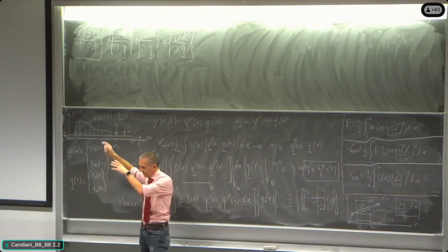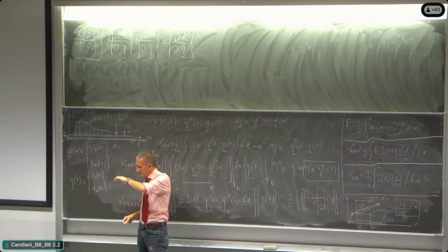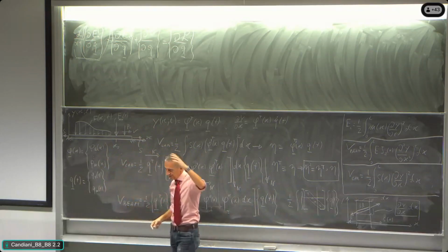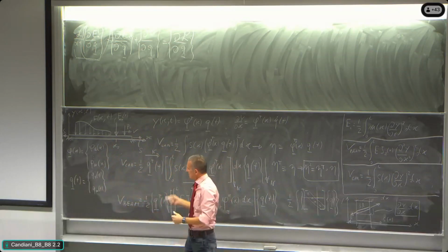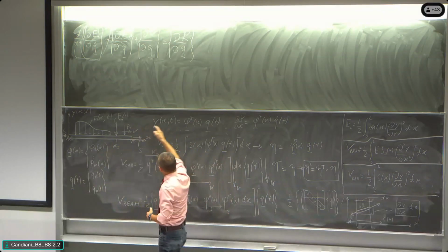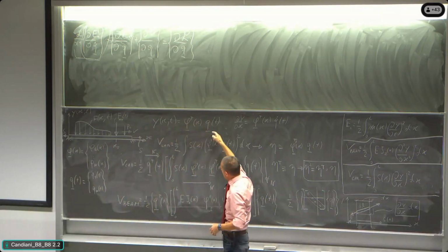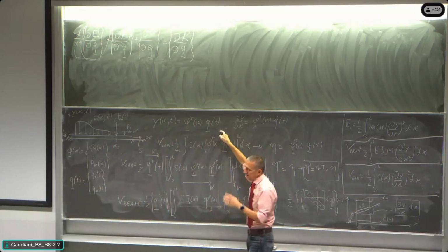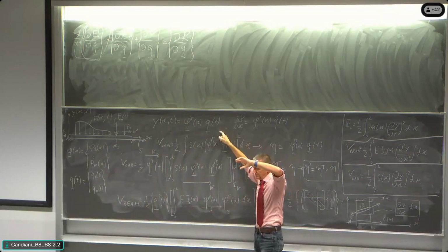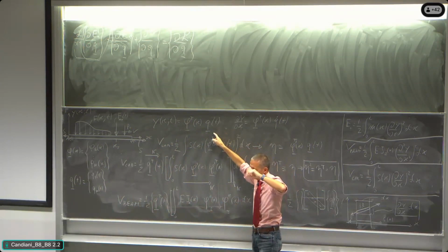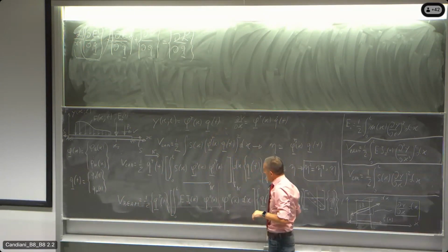So we solve the free motion, we get the modal shapes, and we use those modal shapes to write that the generic displacement of the system is given by the combination of the modal shapes through a newly introduced set of variables, because those are the new variables of the problem.